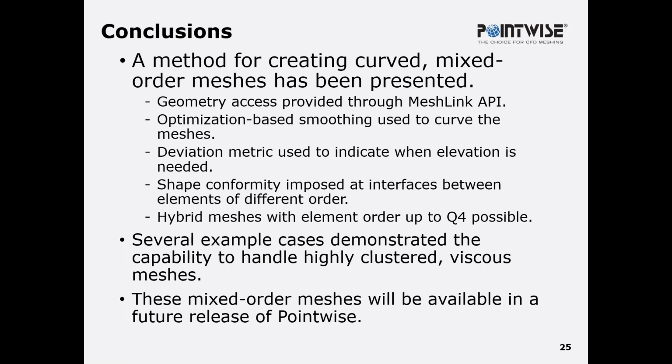Each element surface face conforms with its neighbor. And hybrid meshes with element order up to Q4 are possible. Several example cases have been demonstrated to show that the capability can handle highly clustered viscous meshes with high aspect ratio, high quality cells next to the walls.